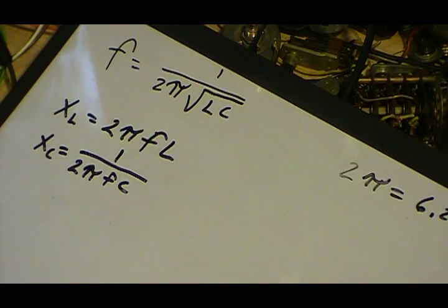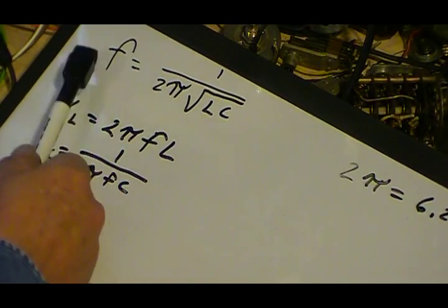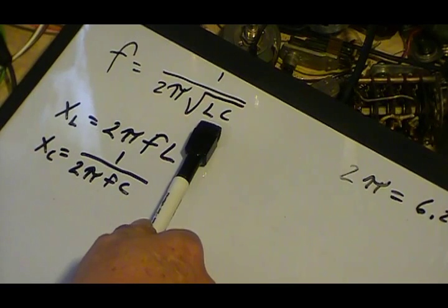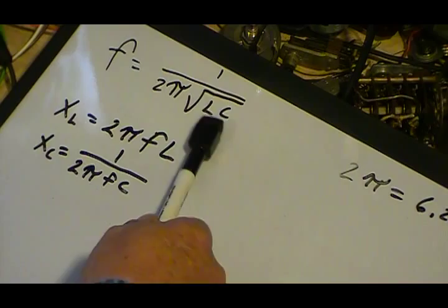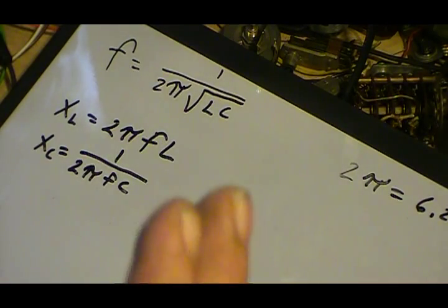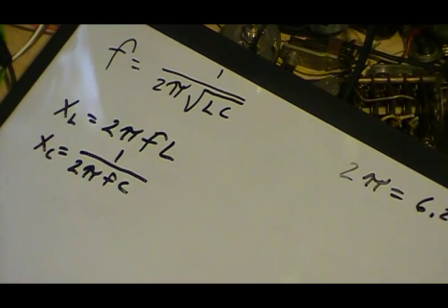And that's kind of important, and it happens in here too, in this formula. Your frequency will change indirectly proportional to what your inductor and capacitor is doing. Now, most radios and most signal generators have fixed inductors or fixed coils, and you tune the radio by changing the capacitance. You rotate the capacitor.